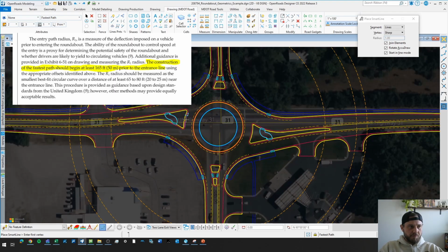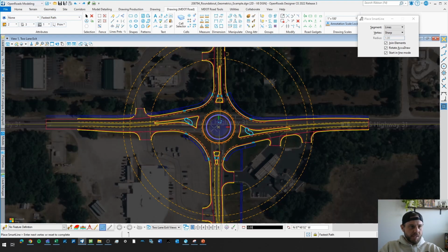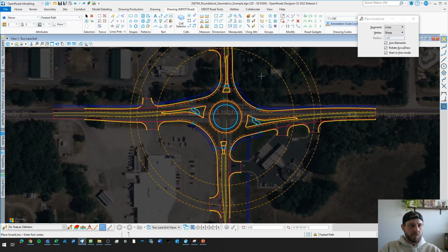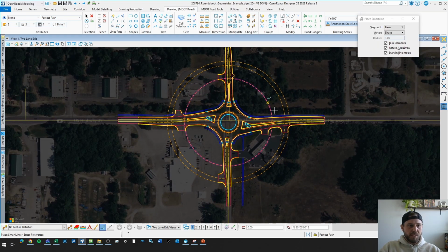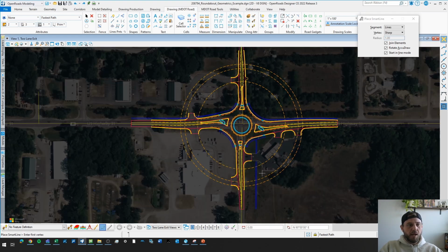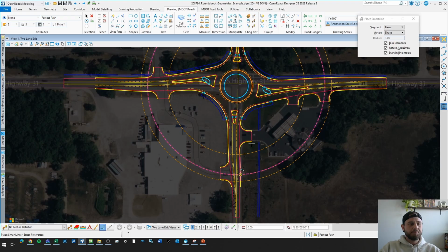It's 165 feet. Obviously on this side, it's a little bit longer. When it comes to the offset, this ends up being 255 because this is a 180 foot ICD, so you got the 90 feet. So I offset that out from the center, 255 feet, and that meets those requirements. And then I did another 75 feet back from there and another 25 feet back from that one. And these are really just going to hold my points before I enter into this.